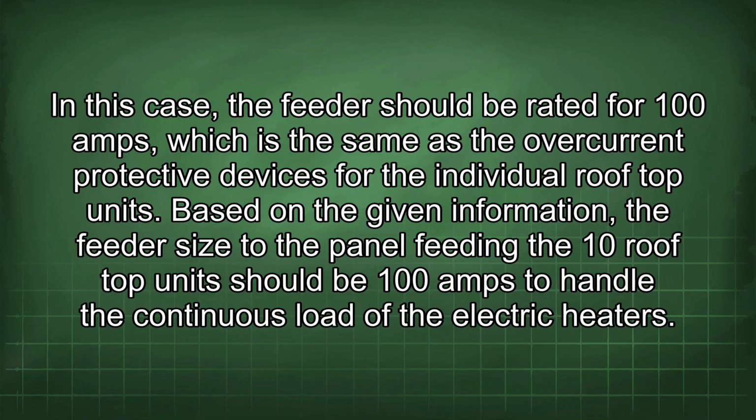Based on the given information, the feeder size to the panel feeding the 10 rooftop units should be 100 amps to handle the continuous load of the electric heaters.